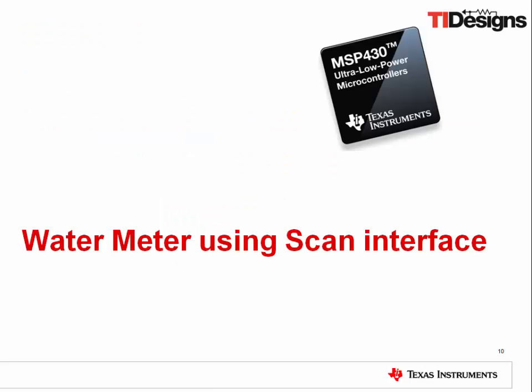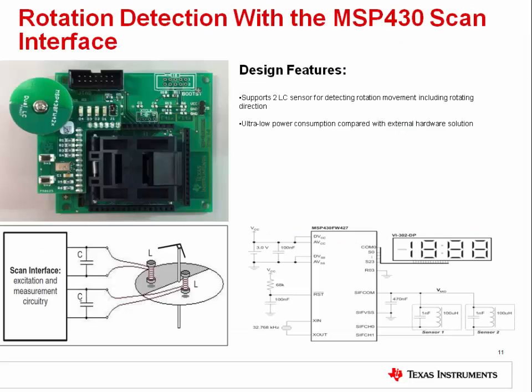The next TI design that we will dig deeper into is the water meter using the SCAN interface. In a battery-operated water meter, battery lifetime over several years is key. One of the challenges is to continuously measure the water flow information while consuming as little energy as possible. The SCAN interface sensing peripheral integrated onto the ultra-low power MSP430 microcontroller is solving this problem.